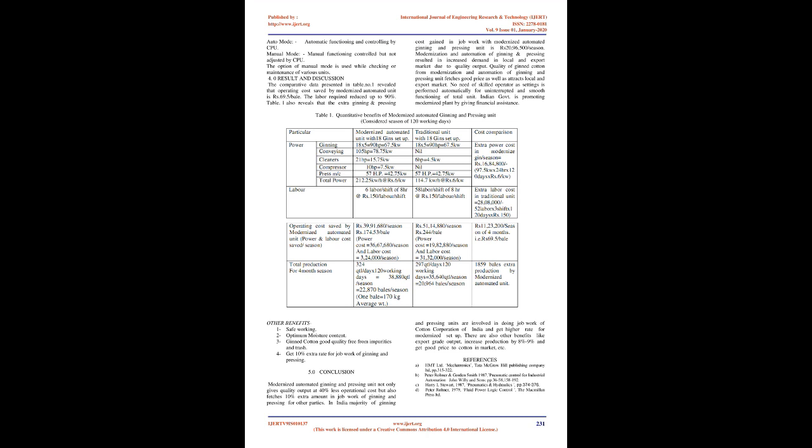7. Programmable Logic Controller. The automatic control unit is a programmable logic controller, PLC, with 100% optically isolated interface to the actuators, limit switches and sensors. The PLC is powered with an inbuilt switching mode power supply, SMPS, with adequate transient and fine filtering. The solenoids and actuators are driven by solid-state switches for long life and better reliability. The motor control contactors, MCC, and overload relays are housed in the same control panel, supported by backup fuses.